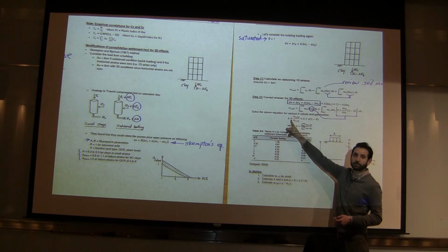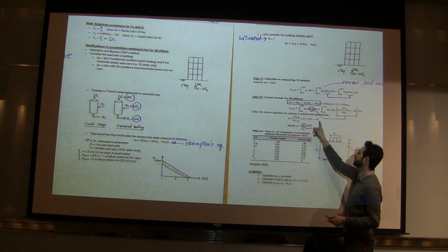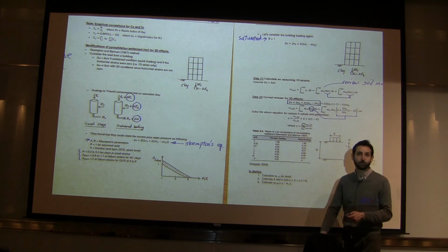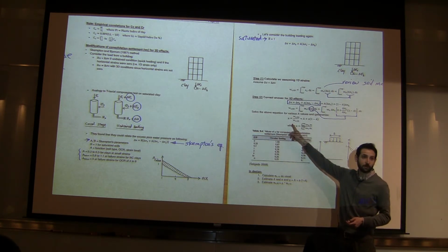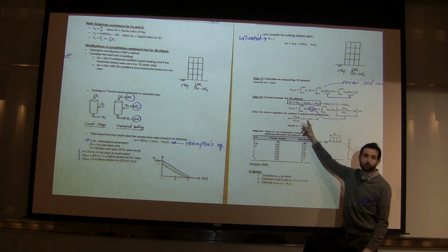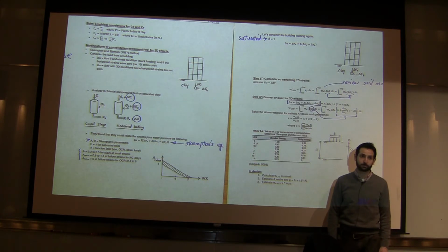The consolidation in 3D over consolidation in 1D is equal to this ratio. That ratio is, let's say, 0.8, which means that you can calculate your 1D consolidation using all the things that we learned in solid mechanics, multiply it by that 0.8, and that gives you the consolidation in 3D.